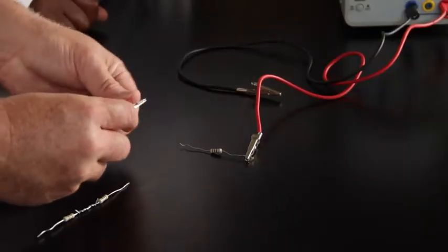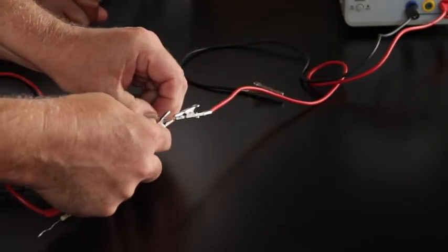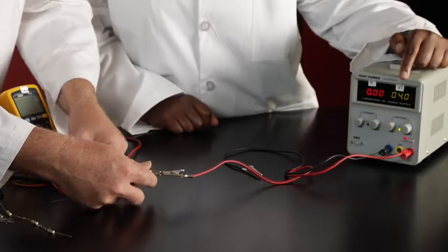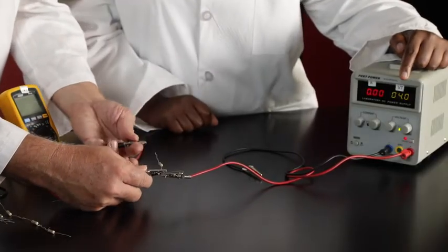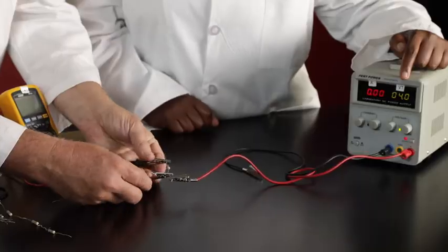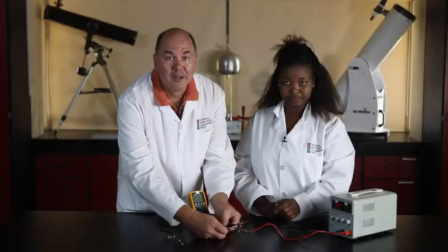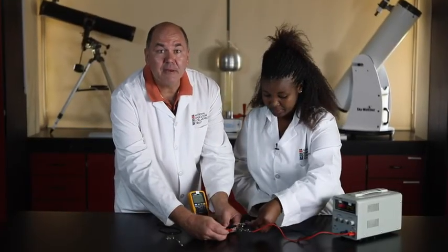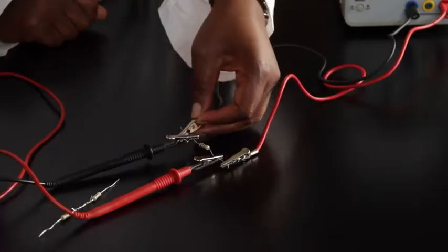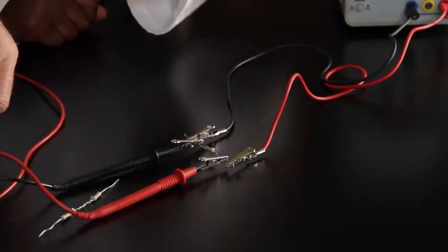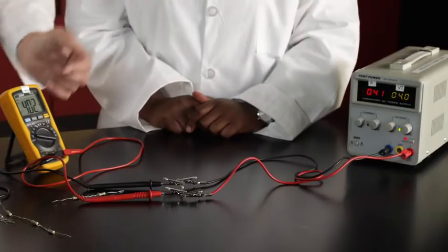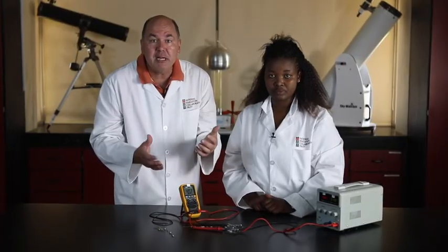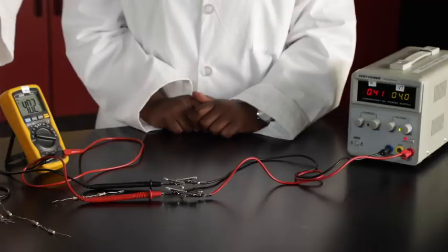And the second voltmeter is connected across the power pack. It reads the potential difference across the battery, which is the same voltage across the series circuit. We're done. Let's see if our circuit is working. You've connected that switch, and I'm going to turn on the voltmeter and see if we get readings. If we get readings, then we'll know the circuit is working.